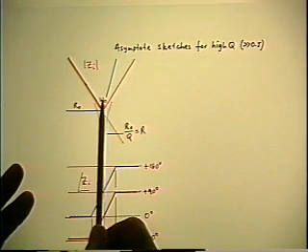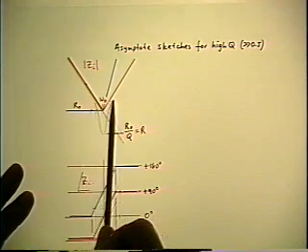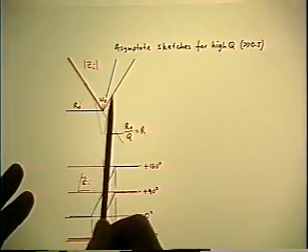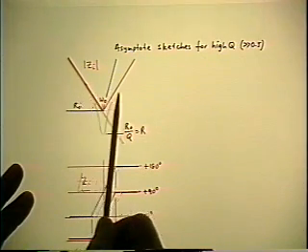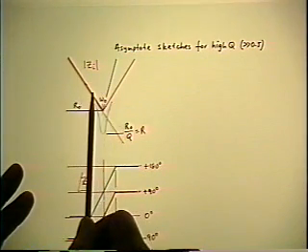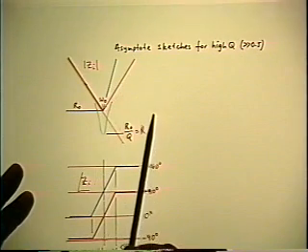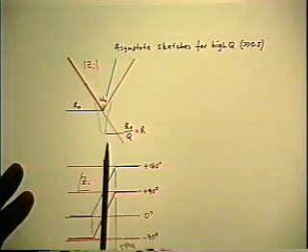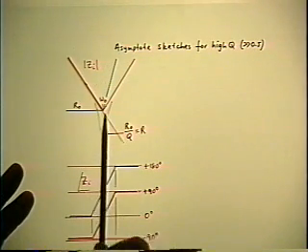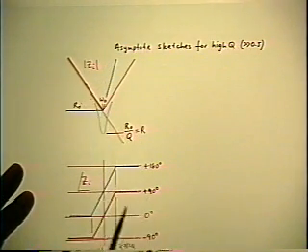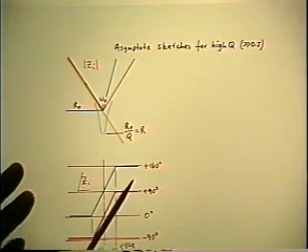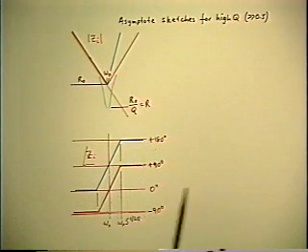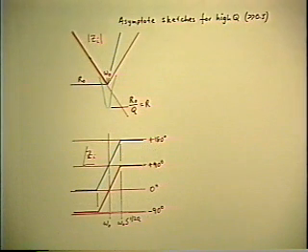And if Q is less than 1, then the roots separate eventually into two real roots, and you'd have a horizontal line joining the two real roots, which would be at Q omega 0 and omega 0 over Q. So you can visualize that sequence of transition as the Q gradually gets smaller and smaller. At the same time, of course, the phase slope would get shallower and shallower and eventually would separate into the 45 degrees per decade separate asymptotes.